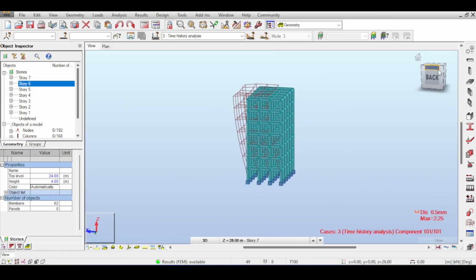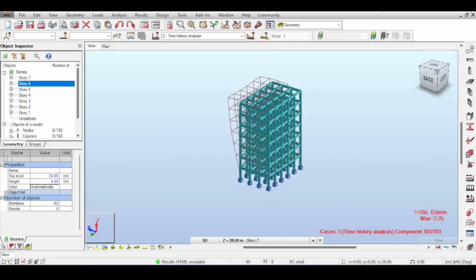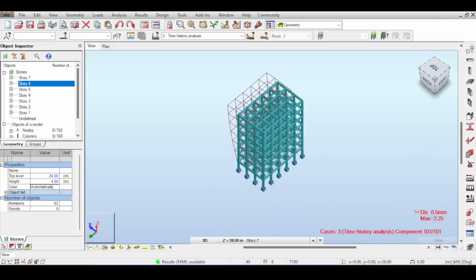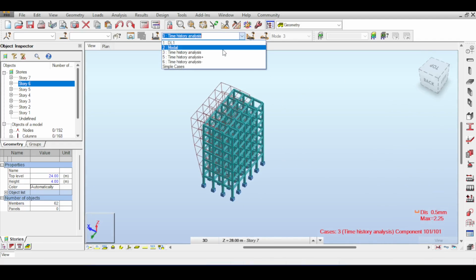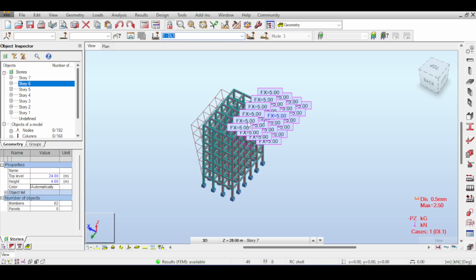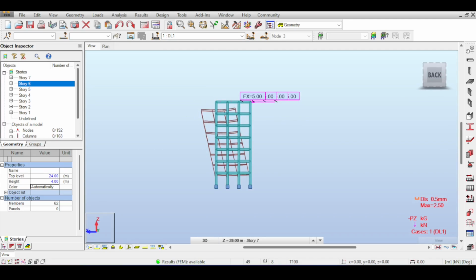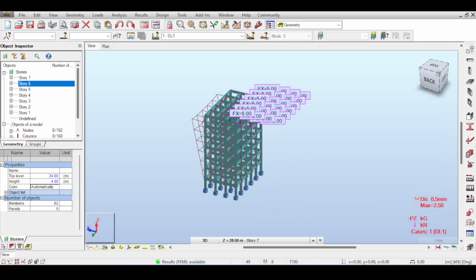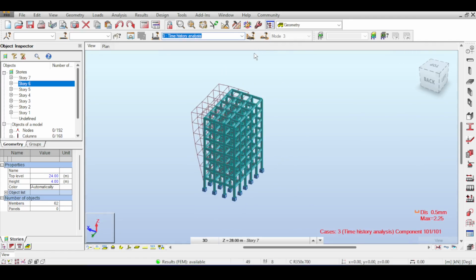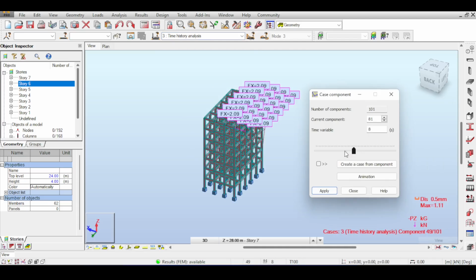So basically, that's it. I think that we have finished something called time history analysis. Just to make sure of one thing, if you take a look at the static force, you can see that the deflection of the static force is 2.5 millimeters, whereas the dynamic has a maximum of, let's take a look, 3.37.